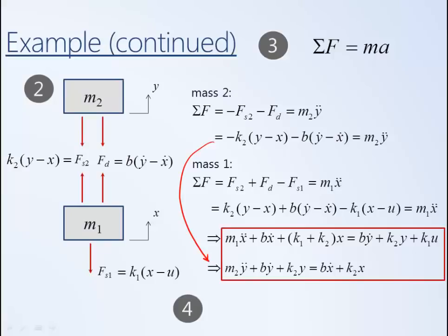The last step in the procedure is to attempt to double check things to make sure that they make physical sense. In general, what you can do is substitute the values for the masses and the stiffness and the damping, and you can see if the behavior makes physical sense, i.e. the rate of decay or the frequency of oscillation, etc.